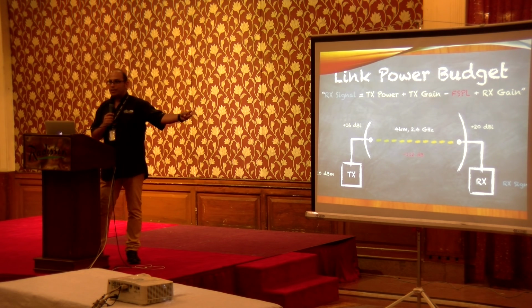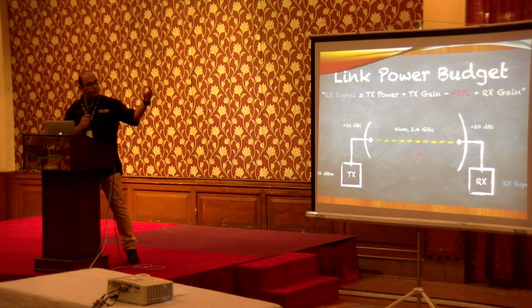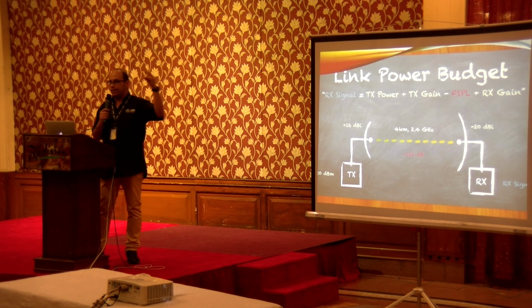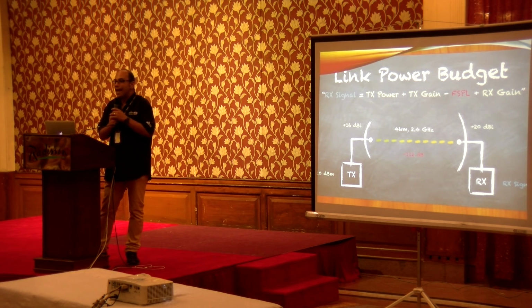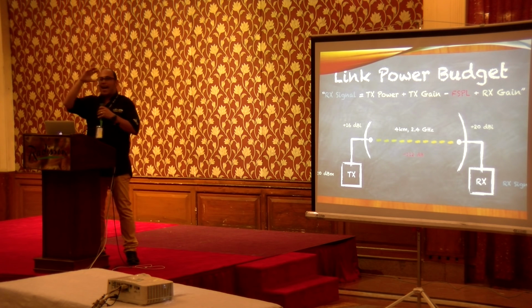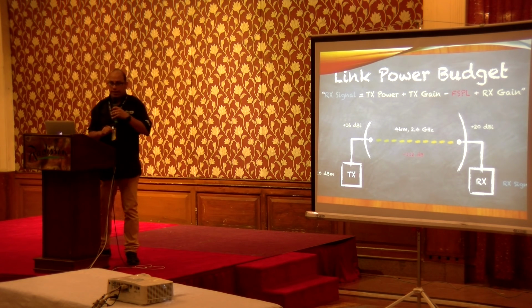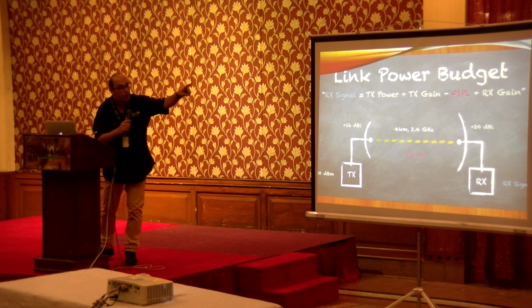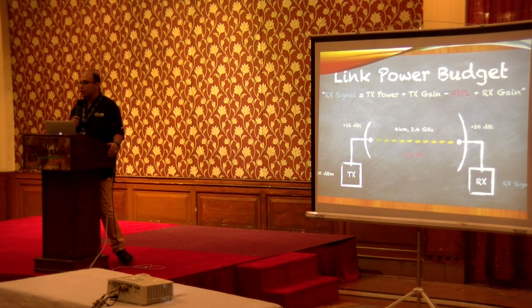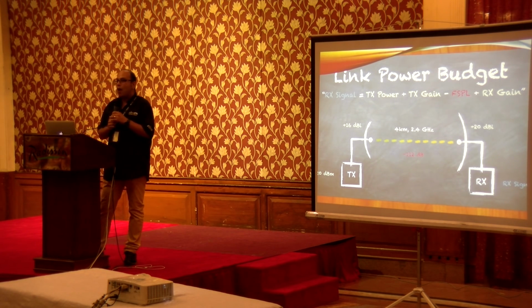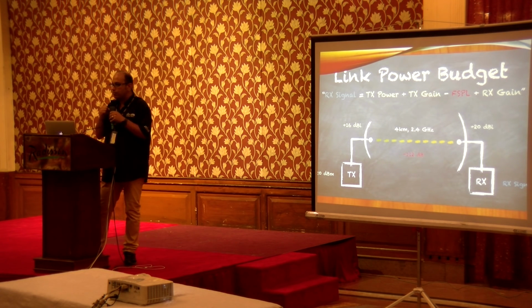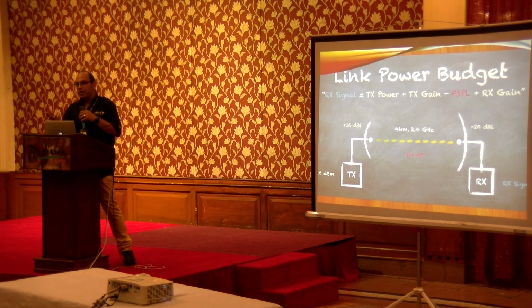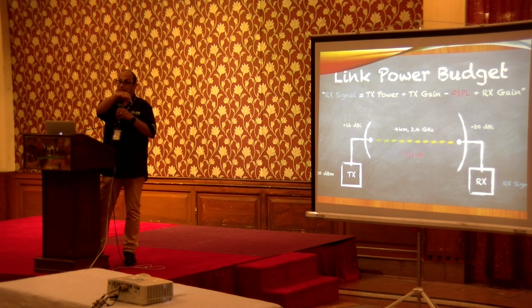Transmit power of transmitter device is important. The gain of transmitter antenna is important. FSPL is important. Now, the signal arrives to receiver side. The gain of the receiver antenna is important. How effective your antenna can listen to the signal. This is the gain, but in the receiver side.